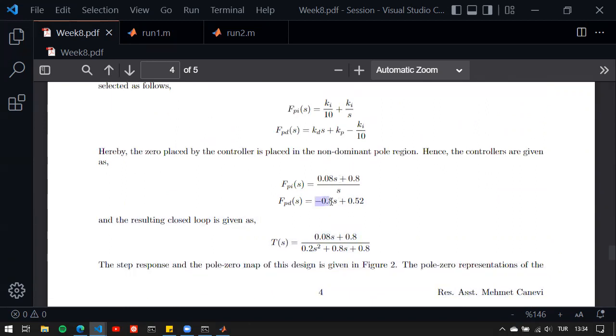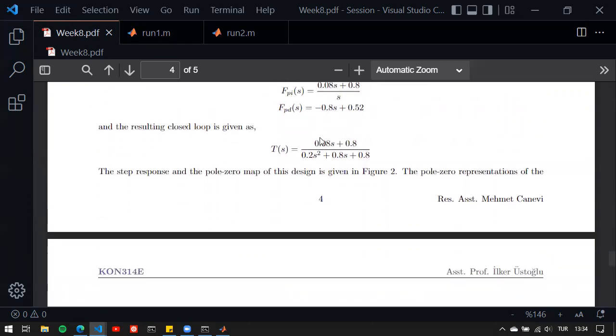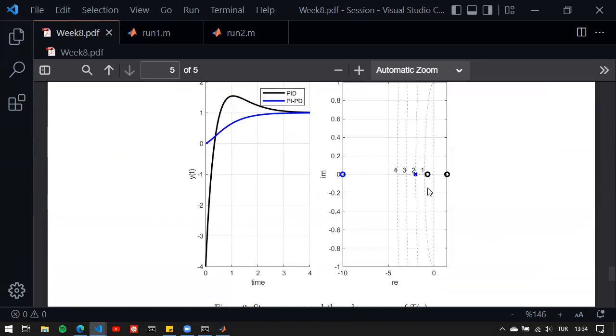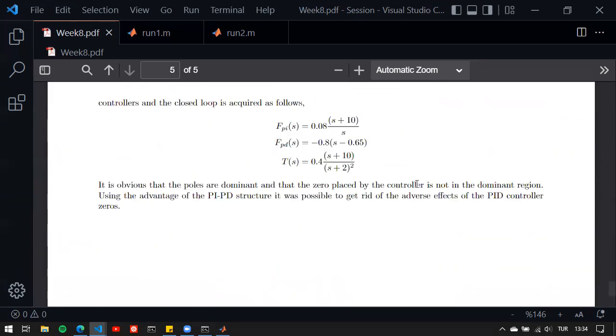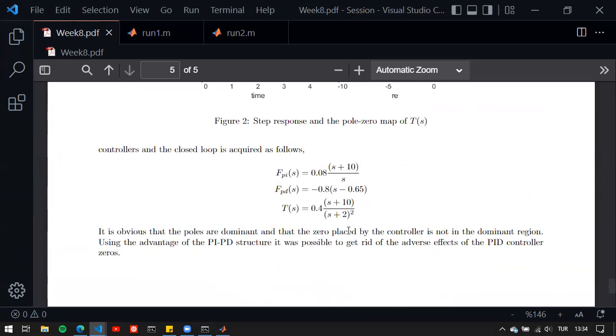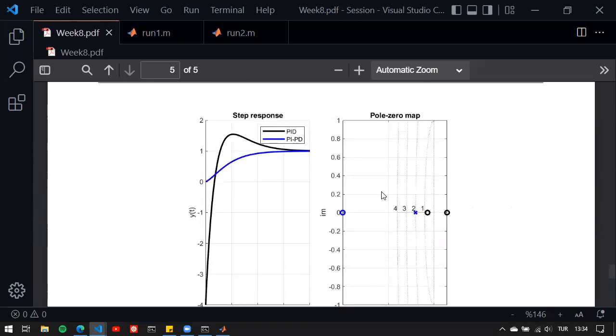And you can see that in this case, we have a negative KD value, but it's not really that big of a problem because it is in the feedback loop. It only maybe affects the type of the loop, if it's a negative feedback or a positive feedback. But other than that, we're not really dealing with that. And then we have this PI controller, and this is a closed loop. Here's again a comparison, and you can see that our closed loop looks like this in this case.